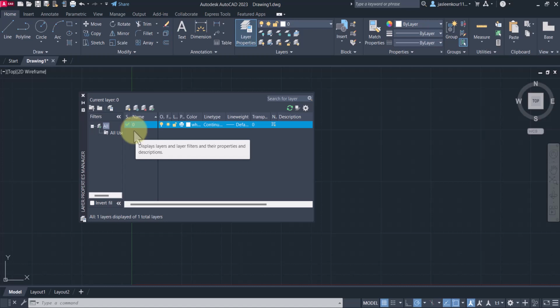Okay. So why I'm using this layer type? Because we are going to draw the object line, the projection line, the hidden line, as well as the continuous chain line. With these layer options, we can draw the diagrams completely without changing the options continuously.